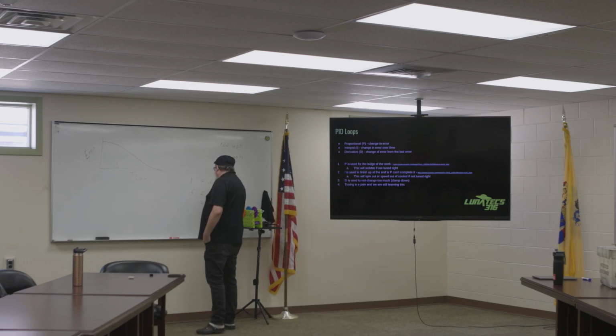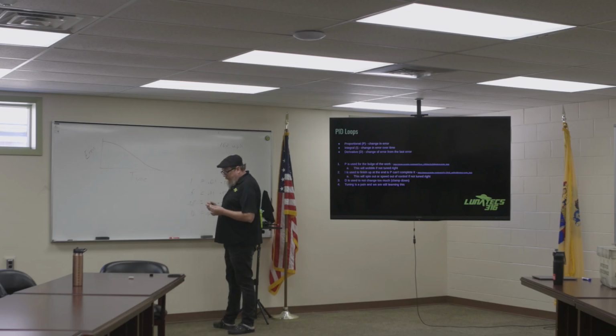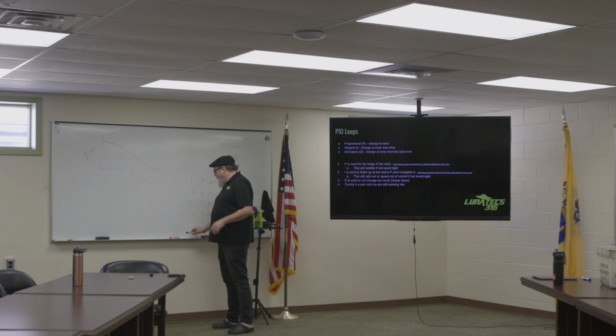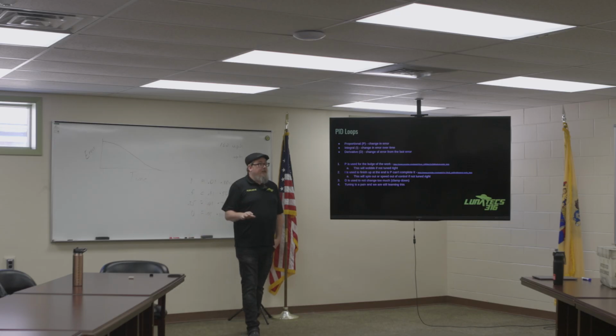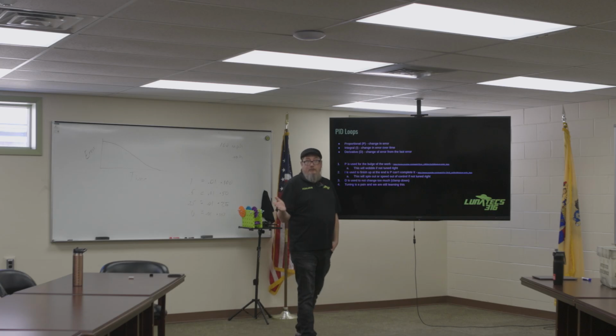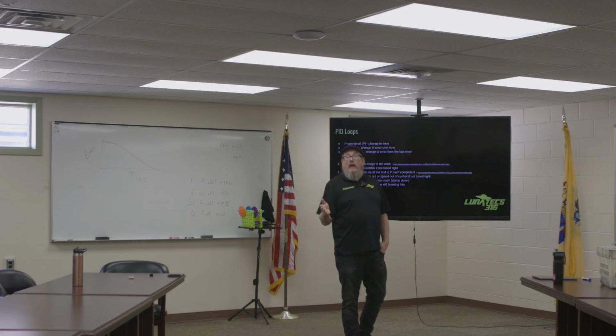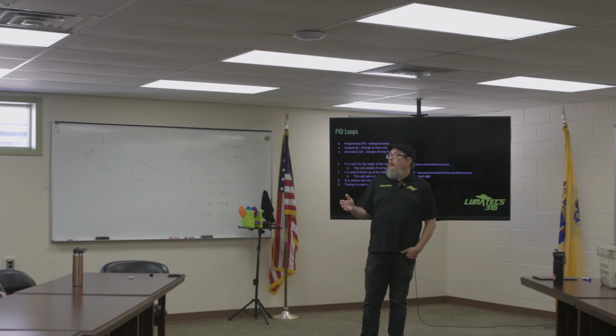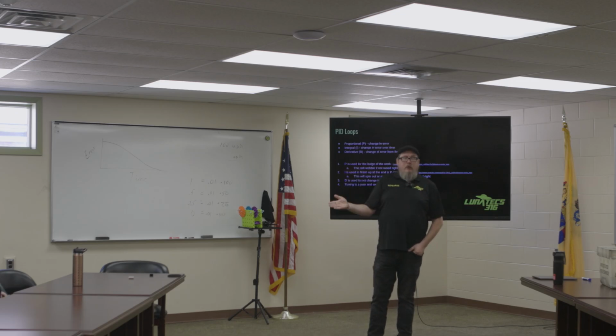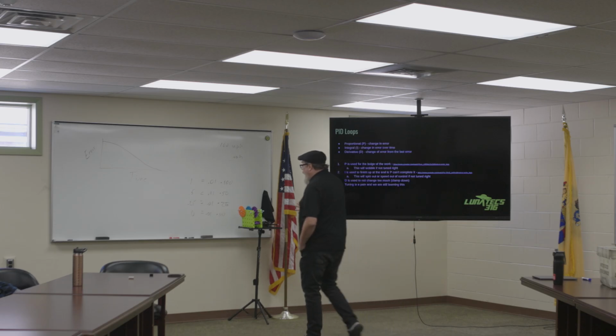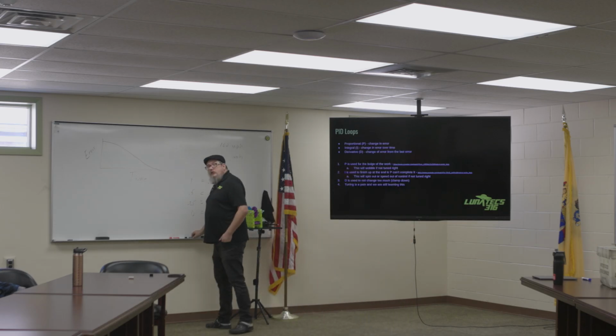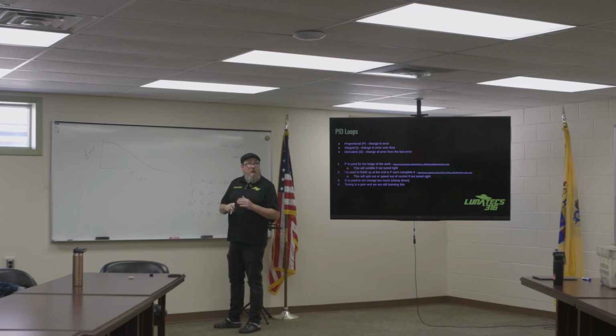So as I keep sampling this, I'm now at an error of 25. What happens when I hit 100? Zeroes out. We'll talk about the implications of that. But what would, in theory, happen if you zeroed out the engine? Gave it 0 power? It'll die. Well, I mean, it won't, but it will stop giving power to what? The car. The car, and so the car will start slowing down. But if you have cruise control on, what would happen if the car started slowing down? It'll speed up to compensate.